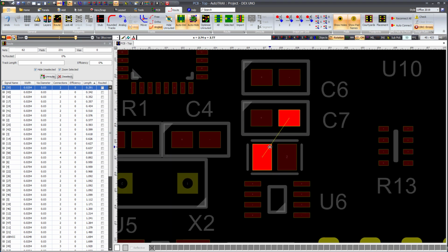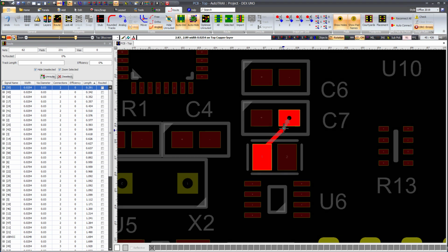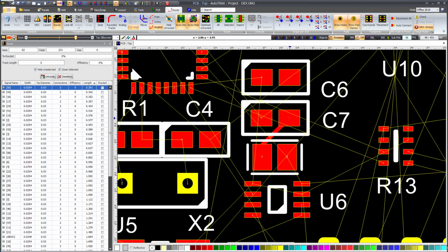I will now quickly route this, as, to be quite honest, it is very easy to route. I hold down the left mouse button over one end of the unrouted net and then drag the mouse so that the mouse cursor is over an end pad, and then release the mouse. This very short PCB net is now routed. Seeing the table of PCB nets in the router panel, the PCB net that I have just routed is now turned green to show that it is fully routed.